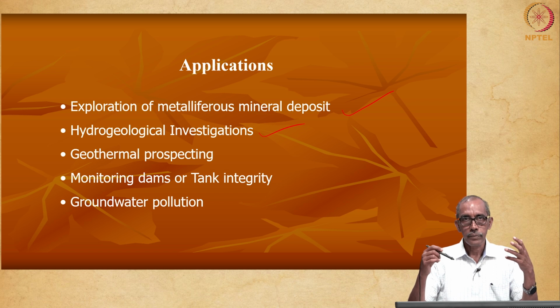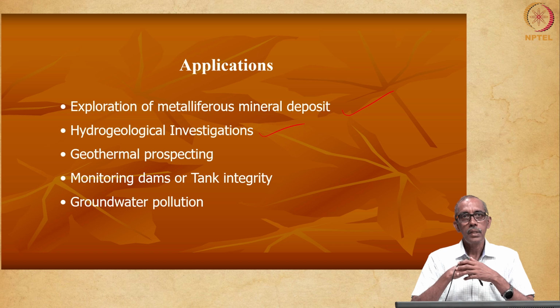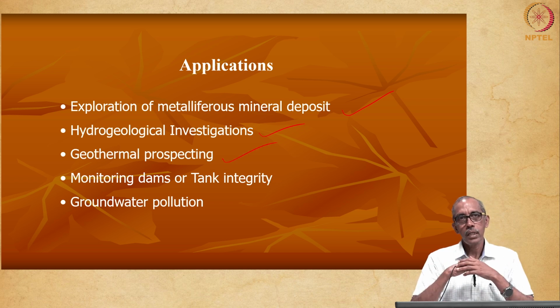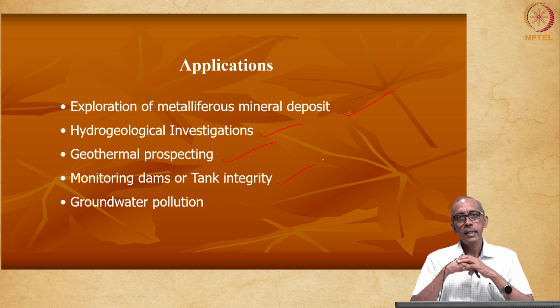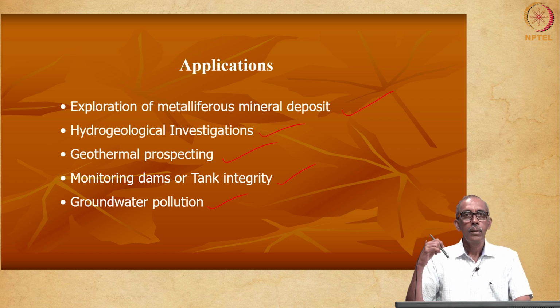If you are a geologist or a water resources engineer, the subsurface groundwater flow can be understood from the self-potential method. Also in geothermal exploration, since self-potential is related to the temperature gradient, it is used in geothermal prospecting. Understanding the integrity of the embankments of tanks and dams is of greater interest to geotechnical engineering. Lastly, it is also used in understanding groundwater pollution.